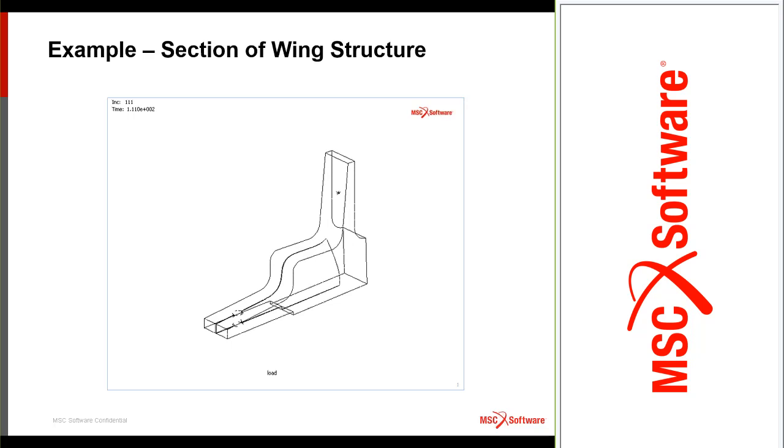And you see on the right-hand side, when we did this model, no one anticipated that we could grow it this far, so it's actually glued on the right-hand side to the rest. And to continue an analysis, we need to make a larger chunk of this one grow through. So this shows that we can successfully do a crack growth analysis in complex geometry.